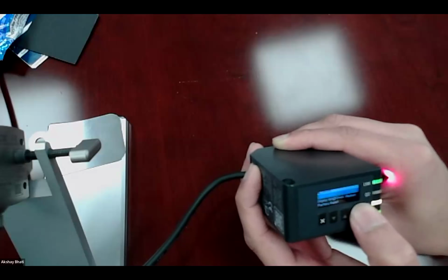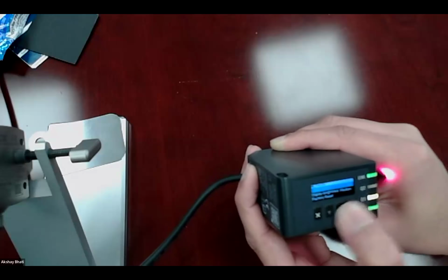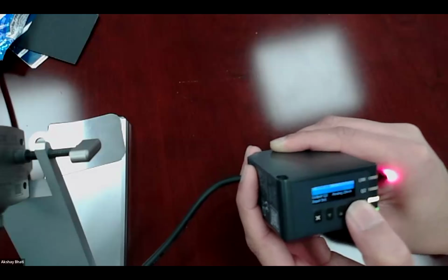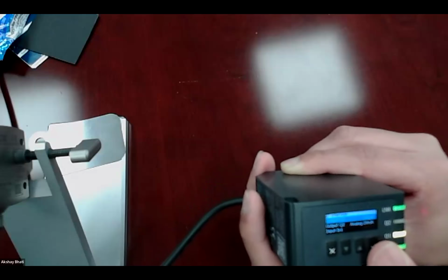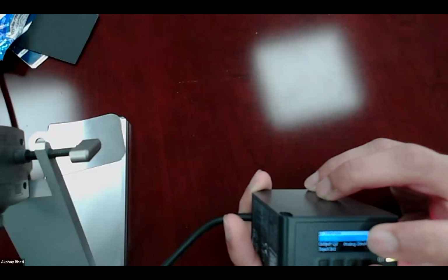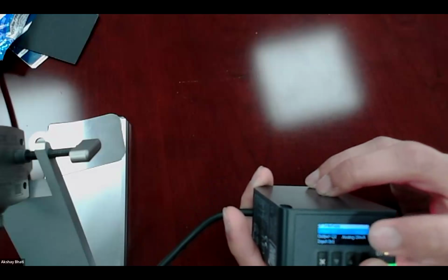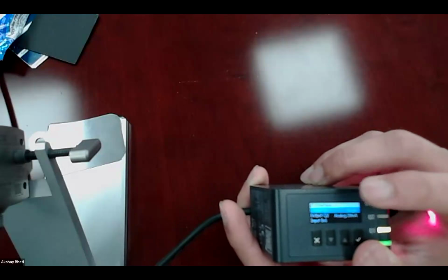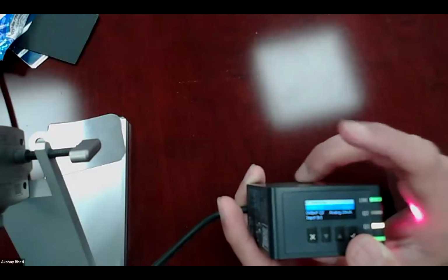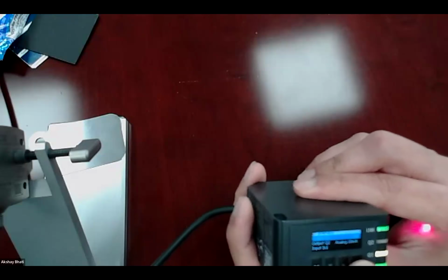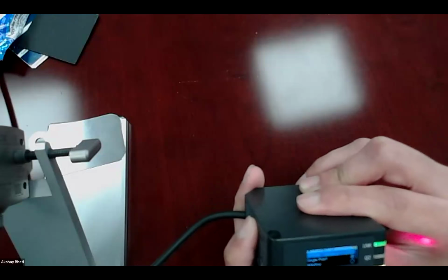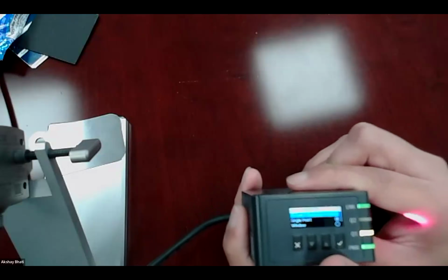The next one is interface. So this is again an important thing. The first one over here says output Q1, output Q2, and input. So you can select input where you can define input, have a teach-in process from the input itself, or you can select your Q1 through the display itself by keying in the value of what distance you need.